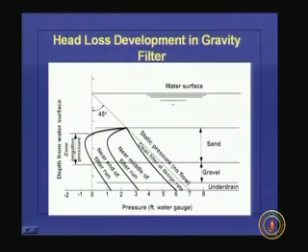After the coagulation flocculation unit or the softening unit, the flocs may not be removed completely from the system. Some flocs will be coming out along with the effluent in the clariflocculator or the softening system. That is not aesthetically appealing, so we have to remove those turbid particles.